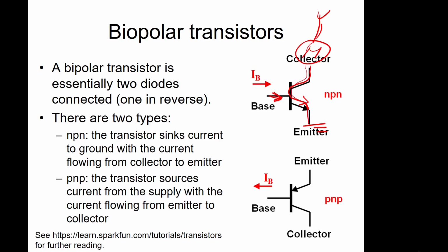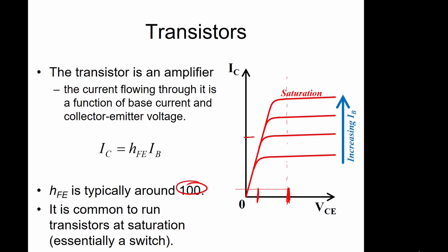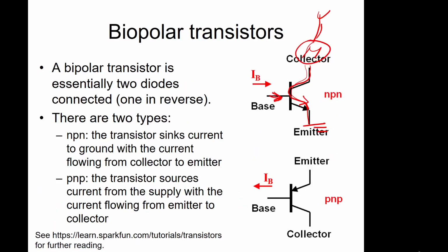The slight problem with this scenario is because we've got a limited amount of gain, in order to drive enough current through here, we also need a significant amount of current through here. And if you're using something like an Arduino to drive this transistor, then that isn't going to be much current coming in here. So ultimately, we're not going to get enough current going through the motor.